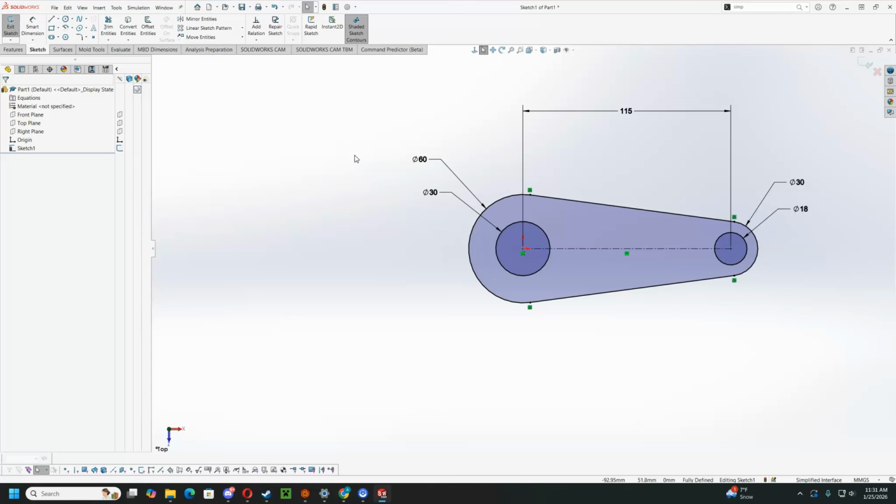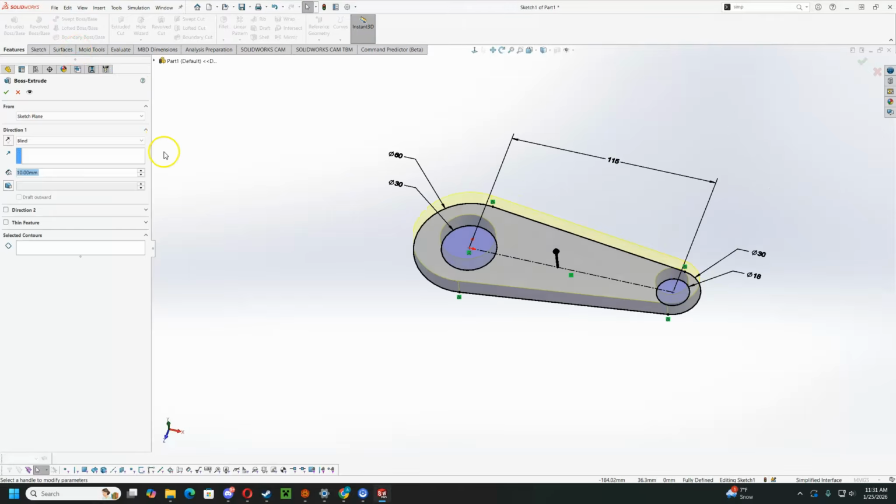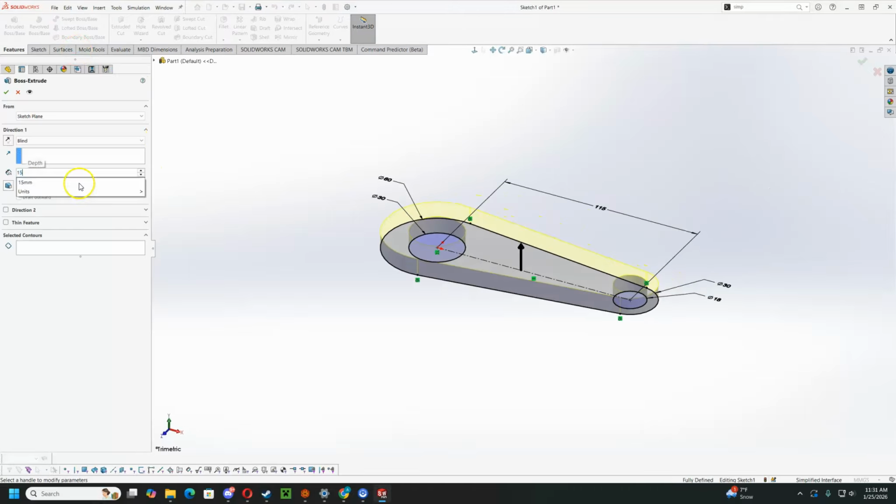Okay. With the base shape drawn, it's time to extrude this up. So the base has a thickness of 15. So I'm going to extrude that for 15. And you notice my arrow is pointing up, extruding up out of the top plane. And I am doing that intentionally. I want my origin to stay on the bottom because that's where all my measurements come from. And we can talk more about that later if needed.